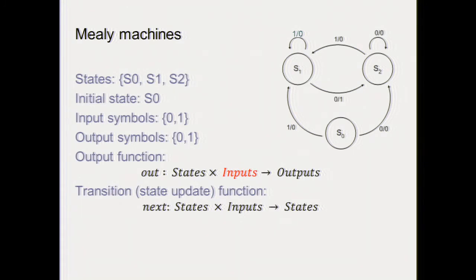Okay, Mealy machines, well, we have to label the transition with the output because now the output depends on the transition, it does not depend on the state. So in fact, you can see that in S0, if you take one transition, the output, let's see, which one? S2, is always 0. So this one is an ill-defined thing because it's equivalent to the Moore machine. So even though the idea was to give it as Mealy, this one is a Moore machine.